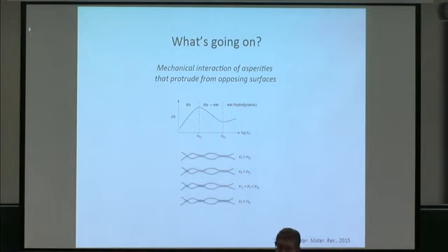So I'm arguing here that at low speeds, we're going to deal with basically creep behavior of asperities in contact. At higher speeds, I'm going to invoke the notion that the velocity is now high enough and the heat so generated through frictional sliding great enough to cause melting localized at certain asperities. Certain asperities will begin to melt. And at still higher speeds, more asperities will melt, until finally one gets into the hydrodynamic region where all asperities have melted, there is a continuous layer of water at the interface and the physics changes.